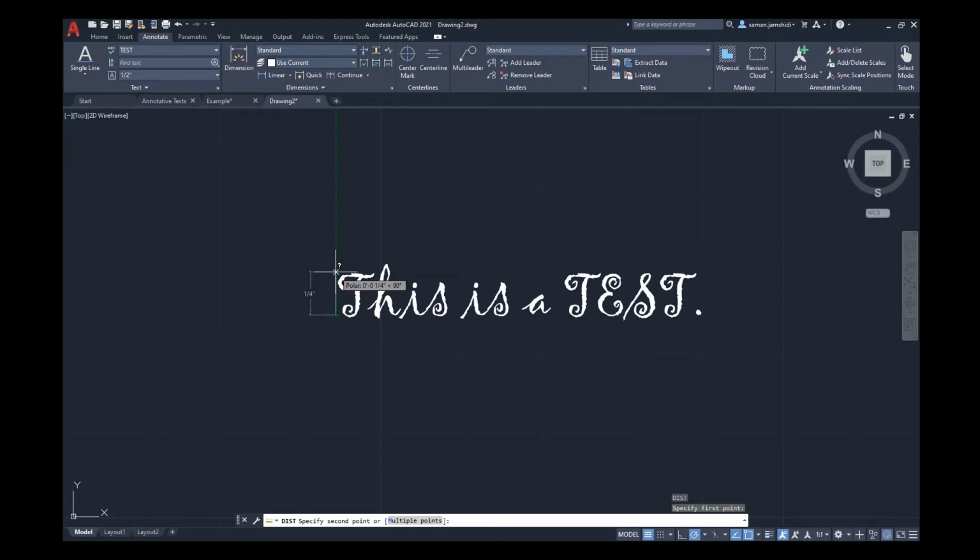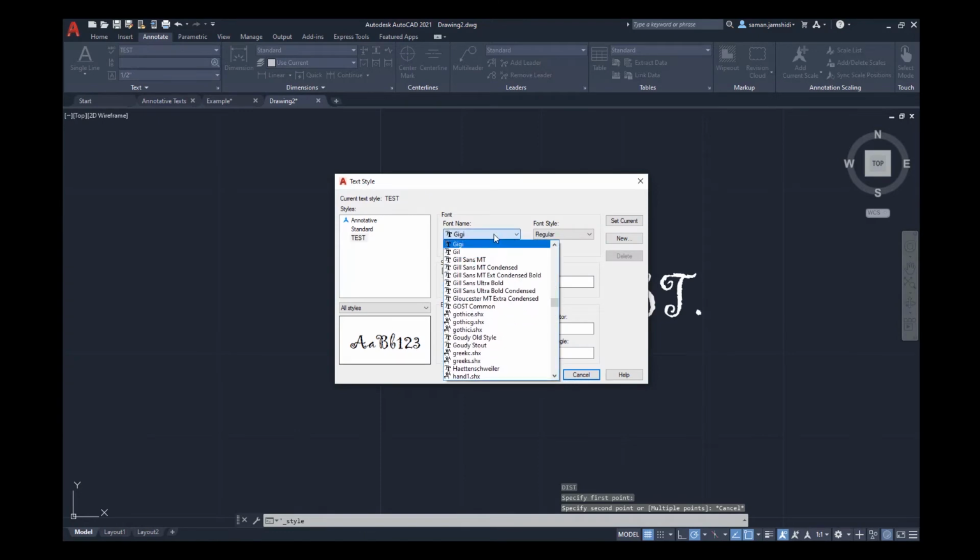It means that you can change the height of a text style and change the whole text within your document with just one adjustment. So that's why you need to use text style instead of any other method that might come to your mind.